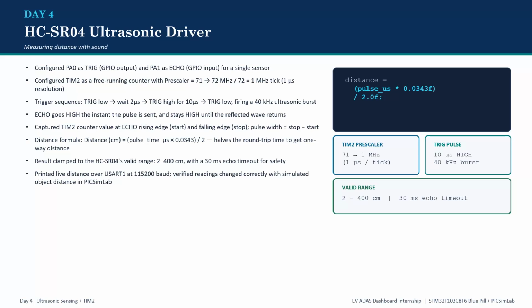The echo pin then goes high the instant the pulse is sent out, and stays high until the reflected sound wave comes back. I captured the timer 2 counter value the moment the echo goes high, that's my start time, and again the moment echo goes low, that's my stop time.